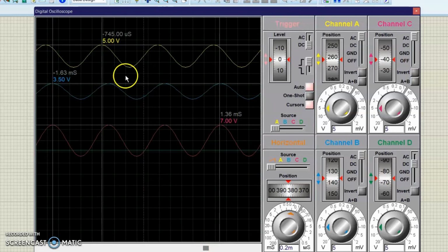From the input side, I get about 5 volts, and then it decreases at 1 kilohertz down to 3.5 volts, which is a small signal, so we need to enlarge it. We have an amplifier with a gain of 2, so 3.5 times 2 we get an output of 7 volts. So this is how we get our signal.